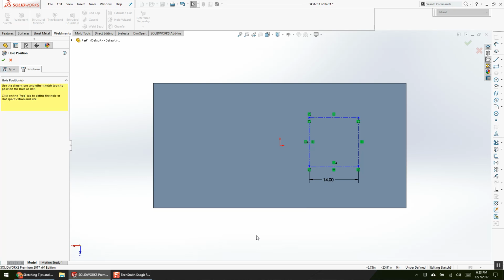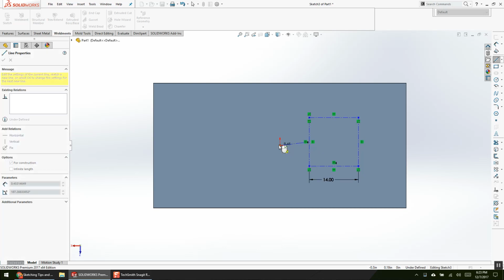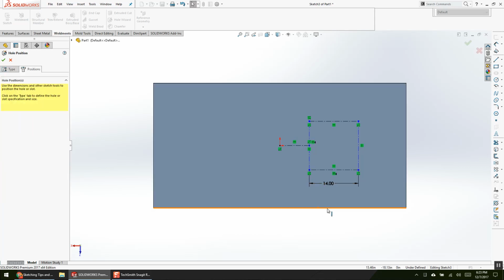The origin. So what happens if my origin was in the corner? You could make it midpoint to the edge, but how reliable is that edge compared to the origin? That edge can very easily disappear and blow things up. That origin will never move because the origin is foundational to the part. So I'm going to take a horizontal center line. Well, I say horizontal, but I drew it on an angle because not everything is drawn perfectly. So I hit my H key, and it's magically horizontal. And I now have the legs aligned in the y-axis exactly in the center, which is the design intent. It's never going to change.